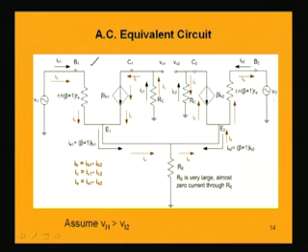Now, if we look into the circuit as a whole, we are having two sources, Vi1 and Vi2, due to which there are currents flowing, and so if we consider Vi1 only, making this Vi2 0, we will be having only the currents due to Vi1, and if I make Vi1 0 and keep Vi2 only, then we are getting the currents due to Vi2 only. As this circuit is a linear circuit, we have to maintain that condition intact. Only under the assumption of the linear circuit we will be proceeding to find out the impact of both the sources on the currents flowing in the circuit.